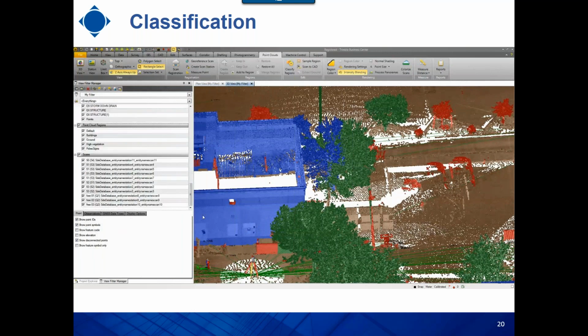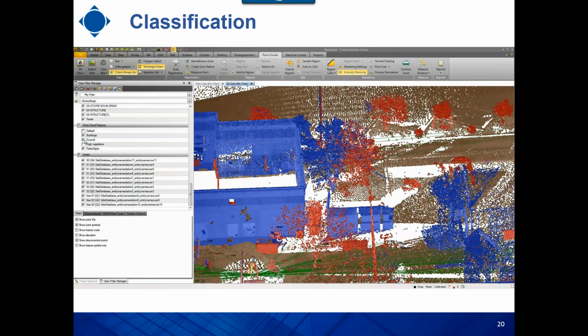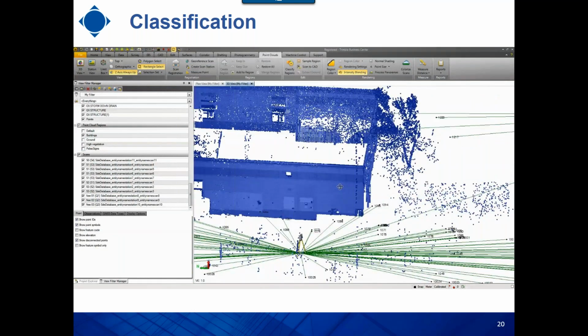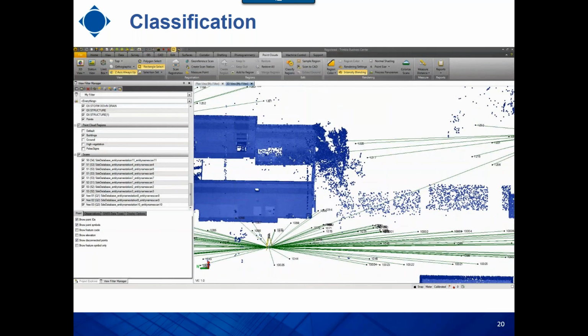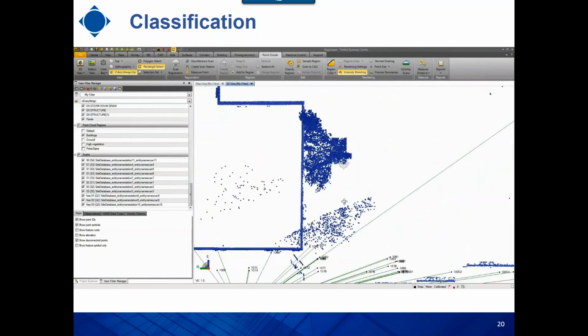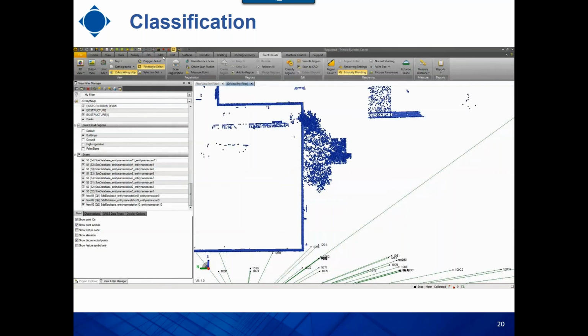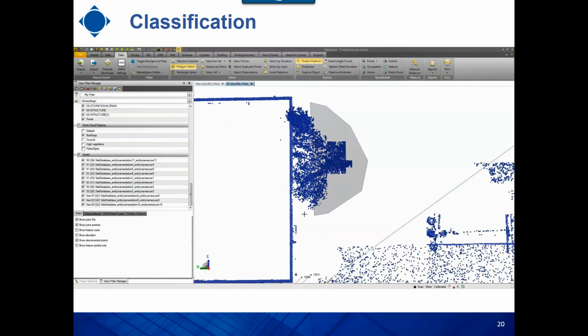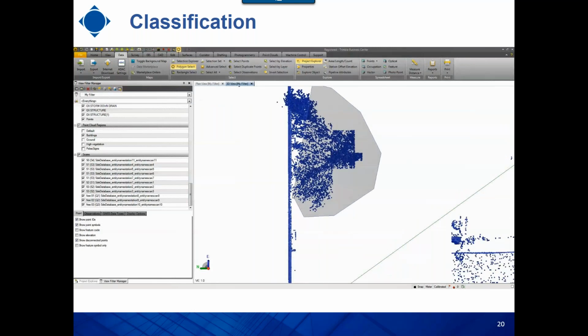Cleaning is one of the tasks of the people who work with the point cloud in the office. So right now, I'm showing you one example of how we can clean up that data and add that wrongly classified tree part to the tree region. I'll go to my 3D view, or I can use limit box tools. In this case, I'm just using the 3D view because it's very easy to look at this data from 3D view. I have my selection in polygon mode. I go around that part of the tree, I select that, and then right after that, there's a command in TBC called add to region, and I will add it to the tree region.